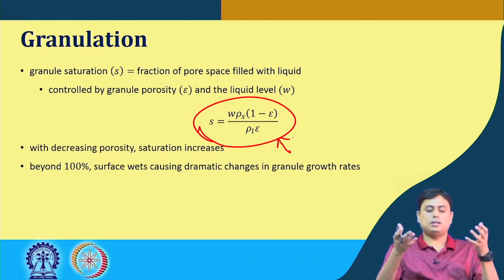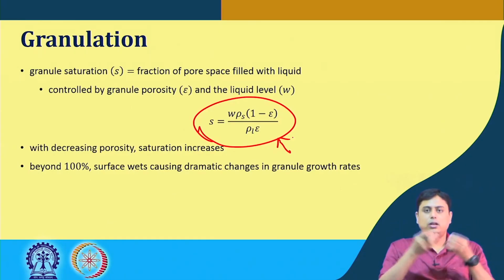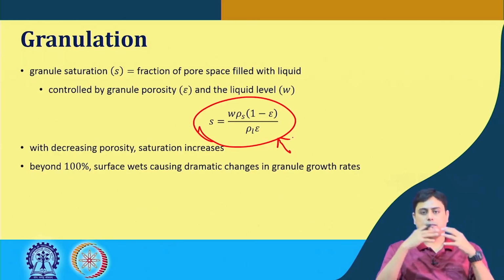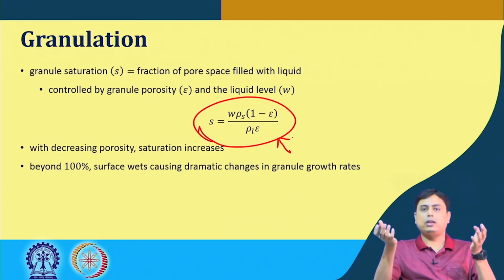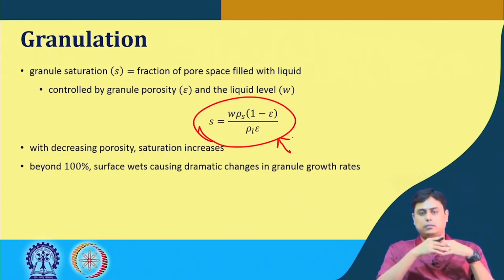But beyond 100% saturation, this liquid comes up to the surface. It causes wetting of the surfaces, and that dramatically changes the granule growth rate, which we will see in the growth mechanism in the next class.